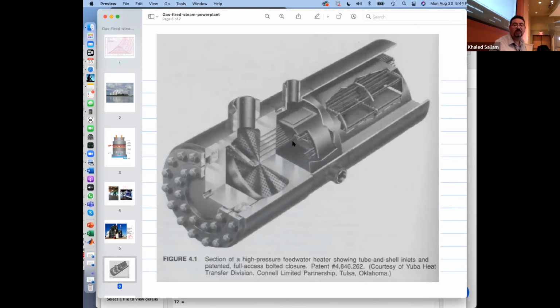You can see it's a bunch of pipes where the water will come in a little bit cold, and leave hot. Who's heating it? Steam. Steam comes here and condenses on the pipes, because for it, those pipes are cold. The water in them is cold. So it condenses on those pipes, right? And becomes liquid that leaves, but in the process, it heats that.